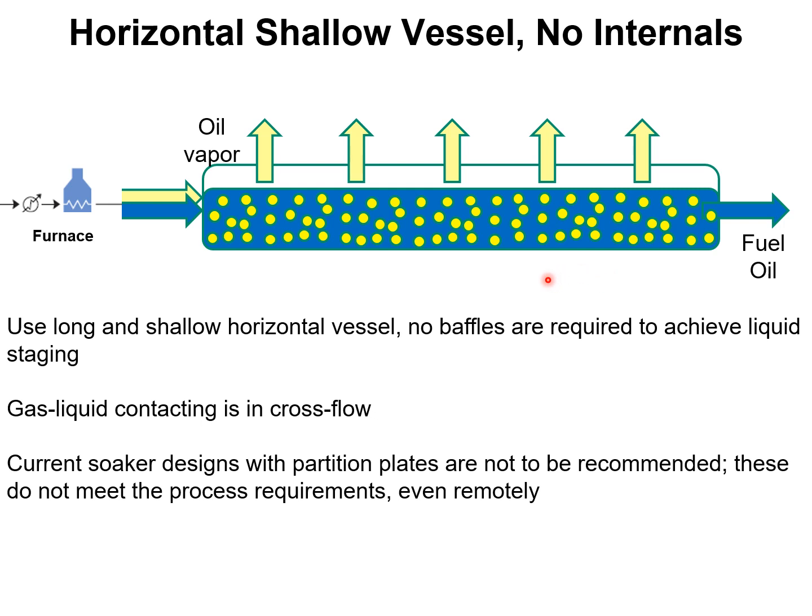There is absolutely no necessity of introducing baffles within the column. Indeed, introduction of baffles is undesirable because this would lead to stagnant regions. So baffles are neither required nor are they desirable.